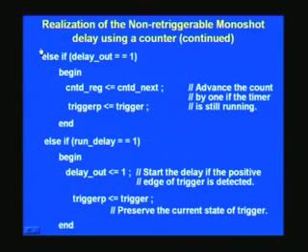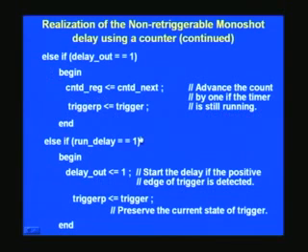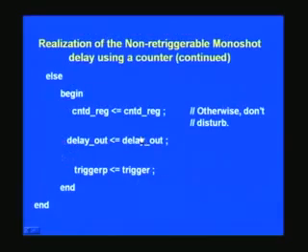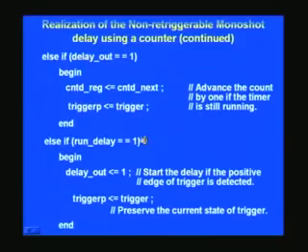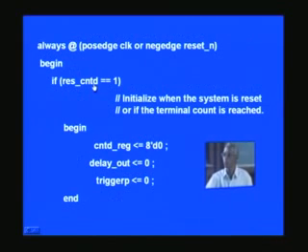We have said earlier that muxes are put cascading each other, and we'll see one more point before we wind up today's lecture, and that is what this implies: it's a priority encoder. See, we have the if statement occurring very first. So if this condition is satisfied, it will execute this, and then quit the whole thing.